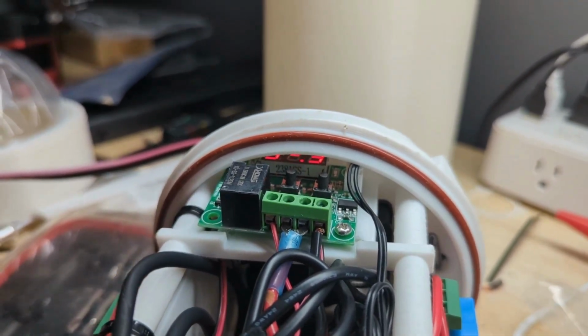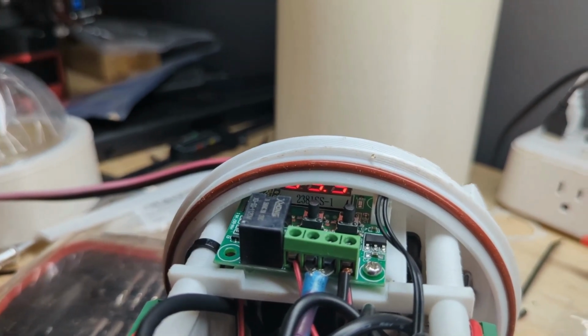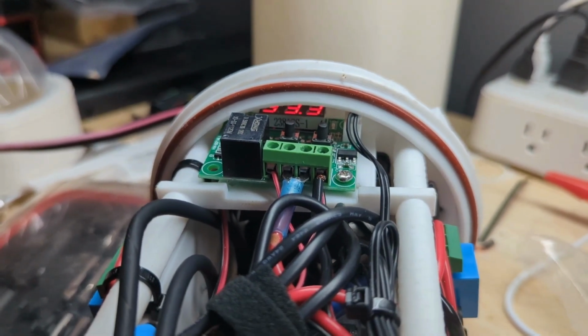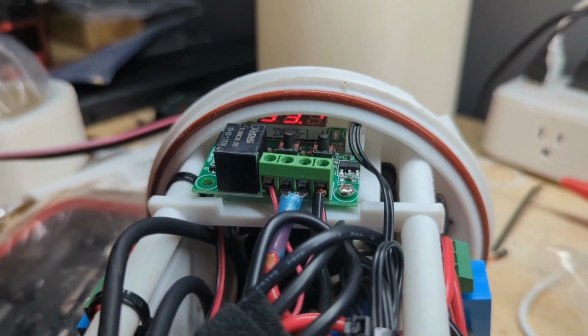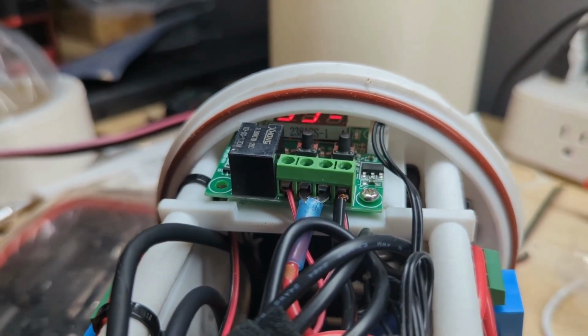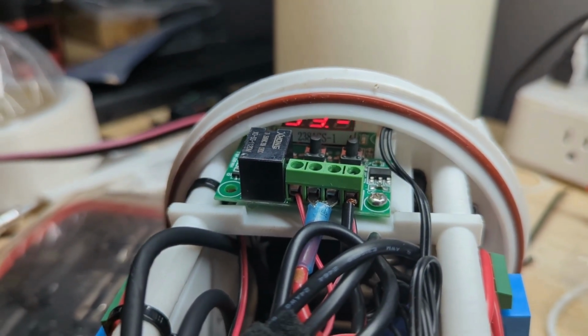If you set it at 95 degrees, once it went up, as soon as you hit 95 degrees again it would shut off, and it would be a constant on-off process, which is not what you really want. So it waits until it hits 2 degrees above your threshold before it turns on and cools the system. Once it gets back down to your threshold, then it turns off.